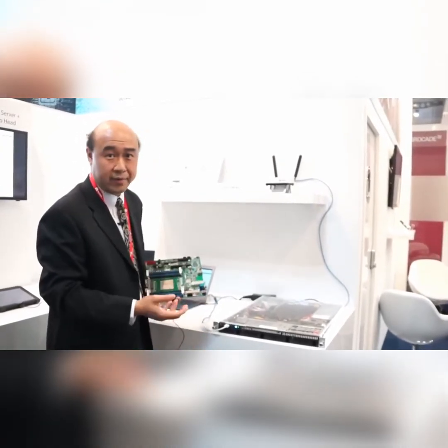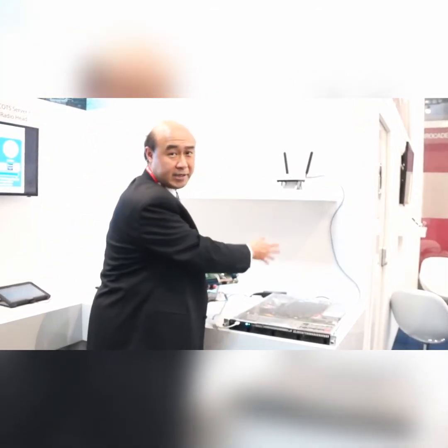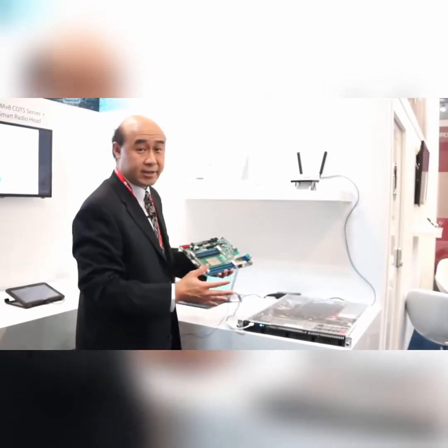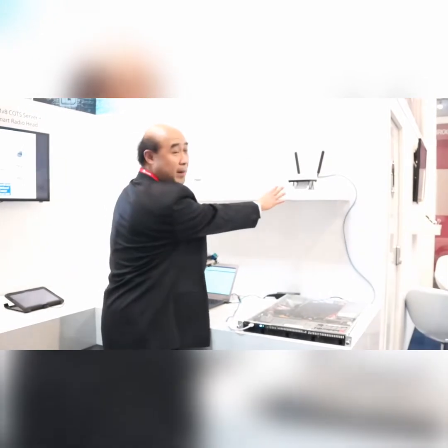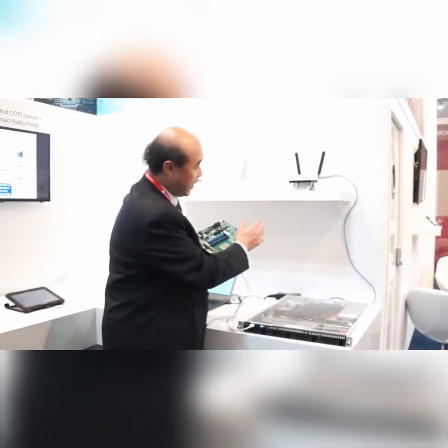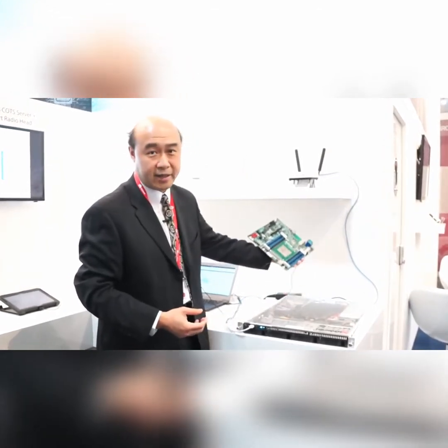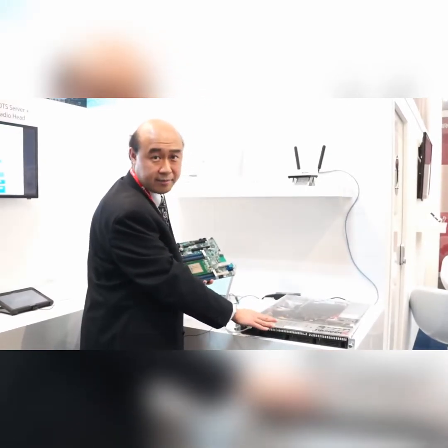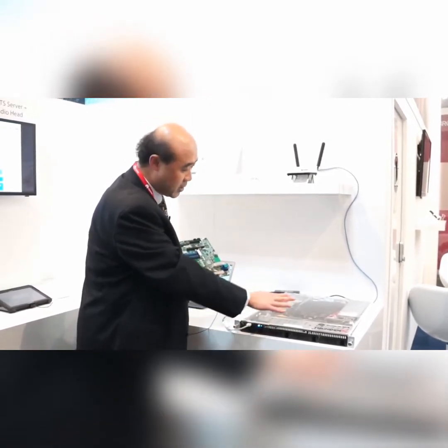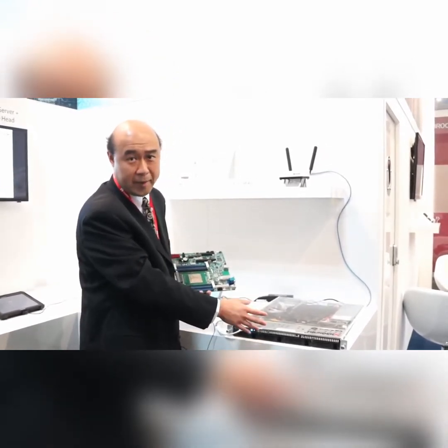In a lot of the current trial or prototype deployments of Cloud RAN, this would have been very expensive fiber optics because of the latency requirement of LTE. In our case, we have some smart processing here in the remote radio head, and that gives much better latency tolerance. So we can use even a basic Ethernet or IP connection between the radio head and a centralized baseband Cloud RAN server. This Cloud RAN server is powered by the Cavium ThunderX ARM 64-bit processor.